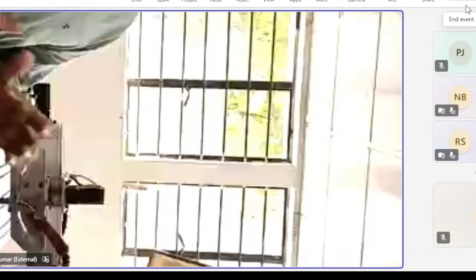So here we are going to deposit a material that is SS308L, a grade of stainless steel, in which the amount of carbon content is very low. That's why it is noted as 308L. So for depositing this, we are using some process parameters. How did we get those process parameters? As I earlier told you, on the basis of some hit and trial experiments on some steady state response, we got some range of the process parameters.